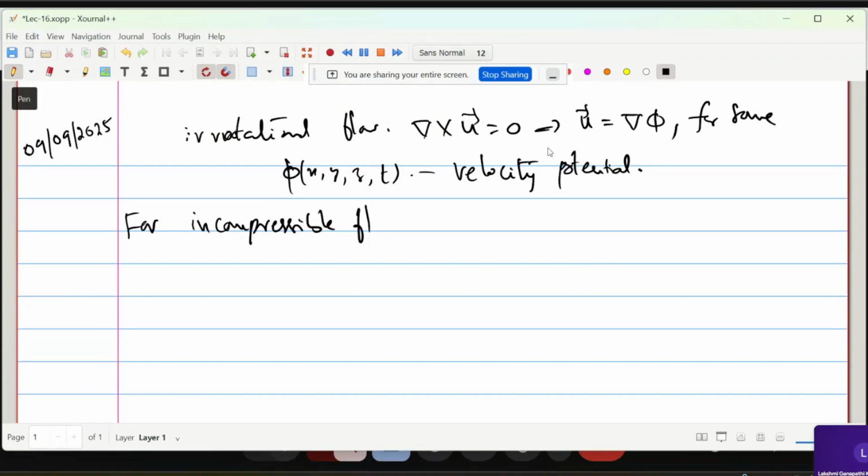So if you consider steady flow, what you are seeing here is u²/2 plus p/ρ plus gz equal to constant. That's what you got now. That is your Bernoulli function. Last class you have seen that B equal to constant. Of course, each constant is different for different streamlines. So that you already integrated out. The remaining equation you solve and get your u, so that the pressure is given in terms of your velocity. That is the advantage of these Bernoulli functions, of course for steady flows only.